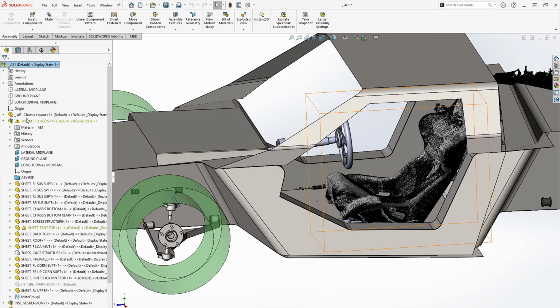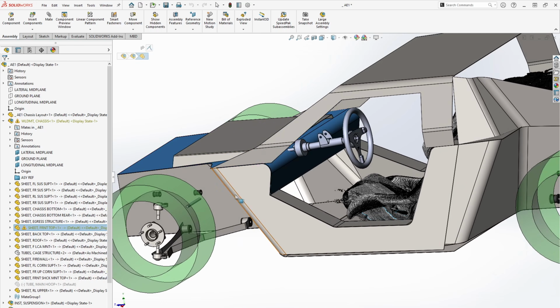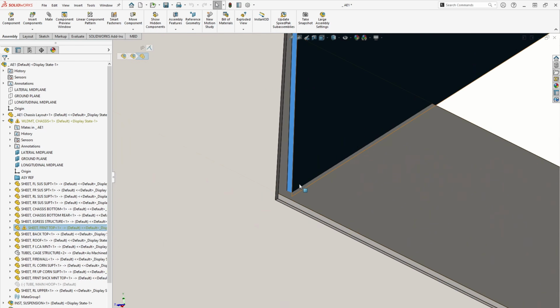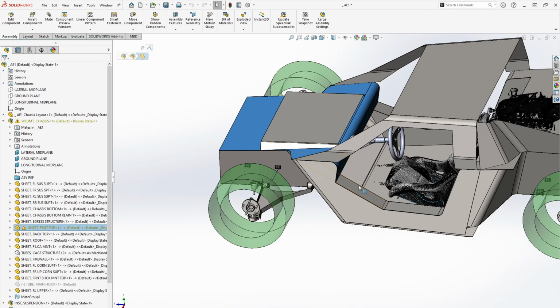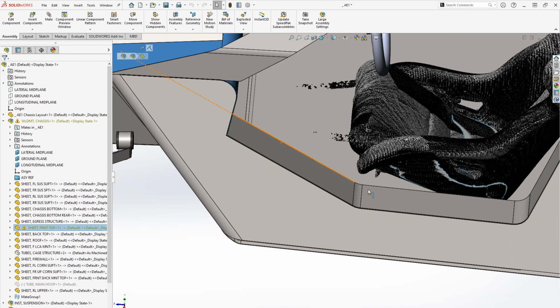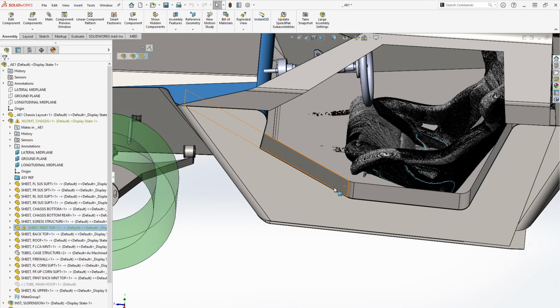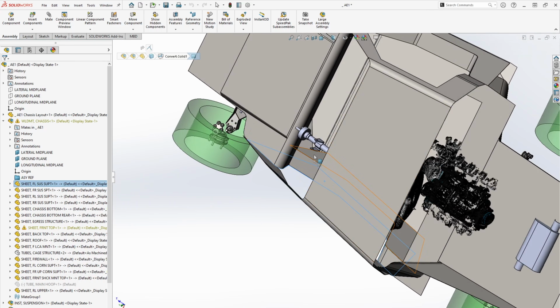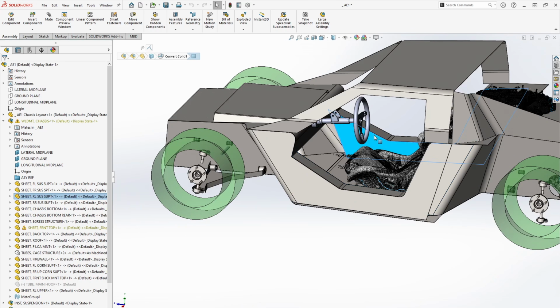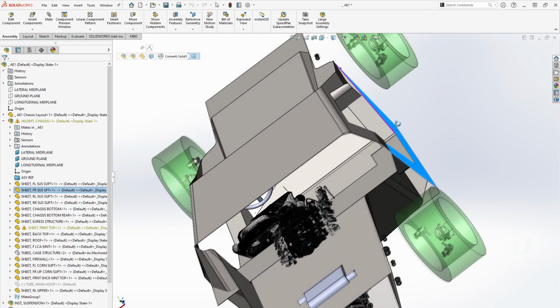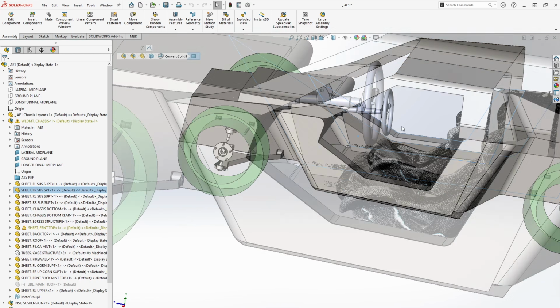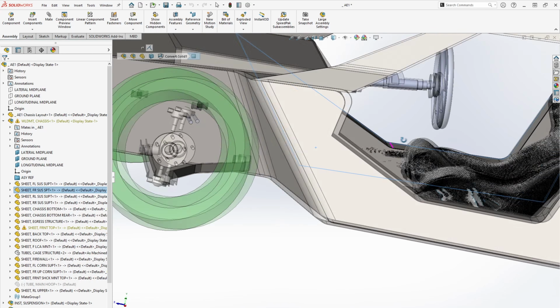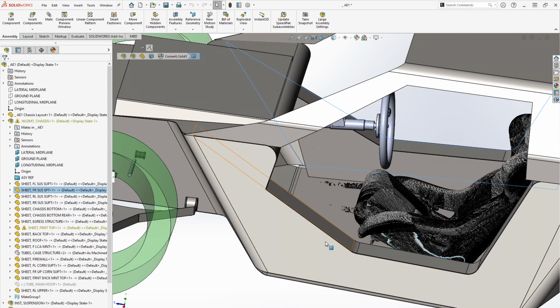Now something I was unhappy over here with the chassis front. I'm guessing I lost a bit of an edge of a 3D sketch right there. That's no big deal, that's for the trimming purpose stuff. But I was able to update 1 dimension, and I had the cutout of 1, 2, 3, 4 plates, or 4 pieces of sheet metal simultaneously changed, so that cutout geometry changed across all of those. And I also had the incline or the bend angle between this plane and this plane change as well.